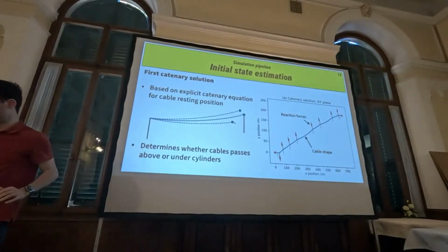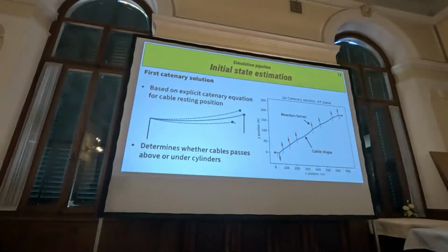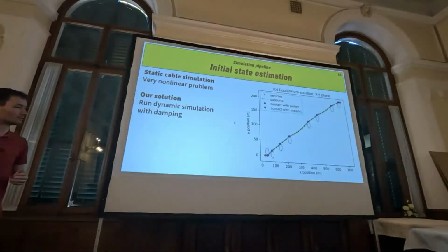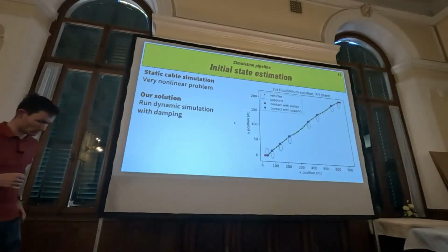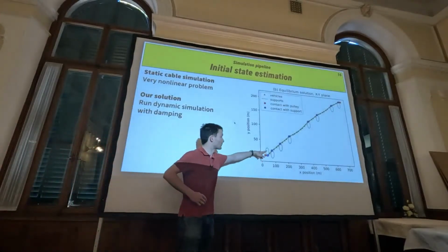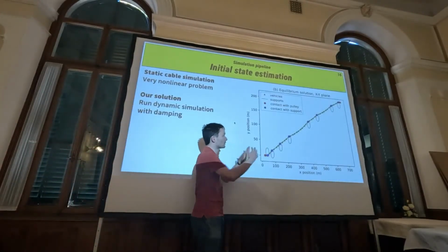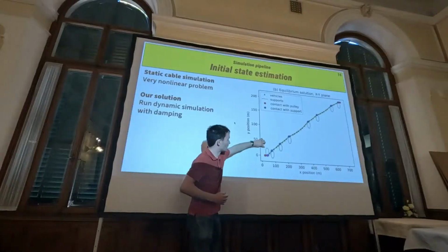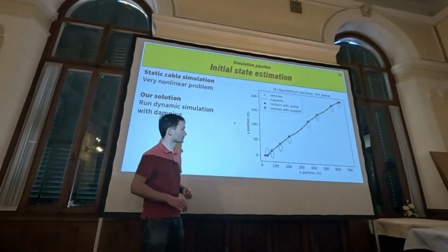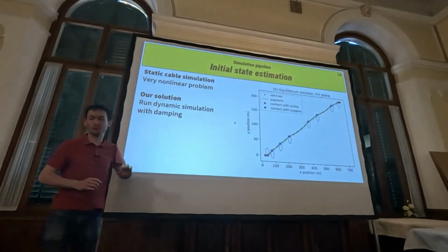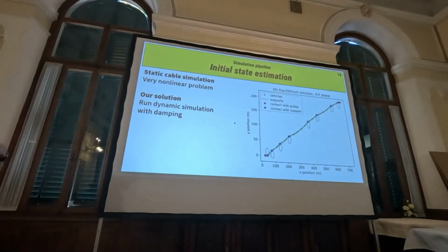It gives a first approximation of the shape of the cable. And then we just relax this approximation to respect the contact with the support, this should be a circle but the image is compressed here, just by running some simulation steps with a big damping so that the cable relaxes to a static equilibrium position.